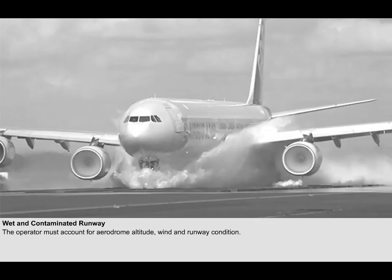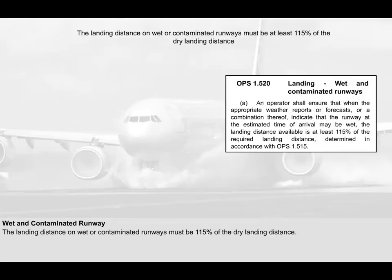An important landing requirement is the one that addresses landing on wet or contaminated runways. EU OPS 1 states that if weather reports or forecasts indicate that the runway at the estimated time of arrival will be wet or contaminated, the landing distance must be at least 115% of the dry landing distance.